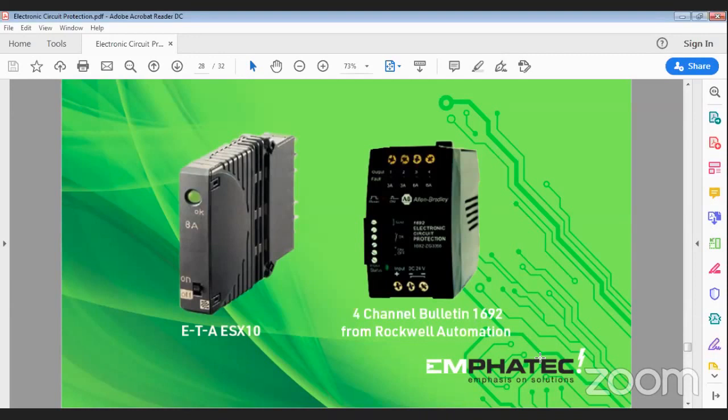The Bulletin 1692 product from Rockwell. This one is a multi-channel unit. So the cost per channel comes down significantly compared to, for example, the ESX10, which is a single channel unit. You can see the ESX10 here has an on-off switch in the front. So that's why they were calling it a breaker, because you can manually turn it on and off, but it doesn't meet the definition of breaker according to electrical codes.